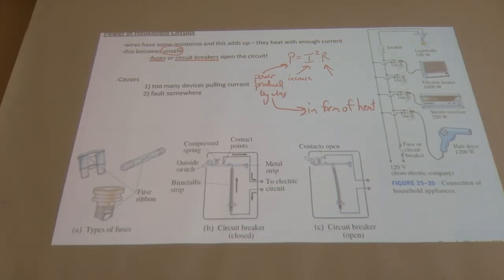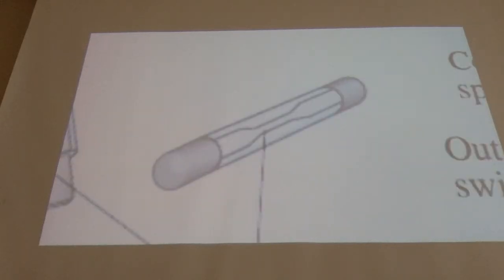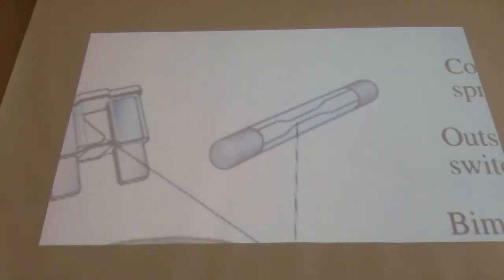So a fuse literally looks something like one of these devices. I'm going to look at this one in particular. Basically, you take this little apparatus and connect a wire to one side and a wire to the other side. Current's flowing through there, and if the current gets too high, this little piece of metal inside melts. It's a physical way to make part of your circuit safely just go away. If that melts, there's no connection between these two wires on the end, and the current can't go through anymore. So that's kind of nice, okay? That's an example of a fuse.